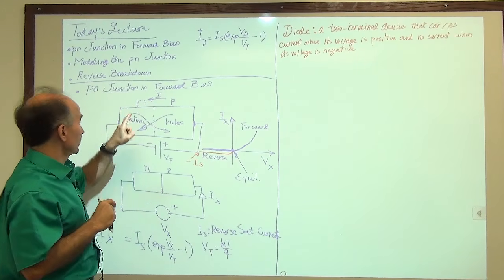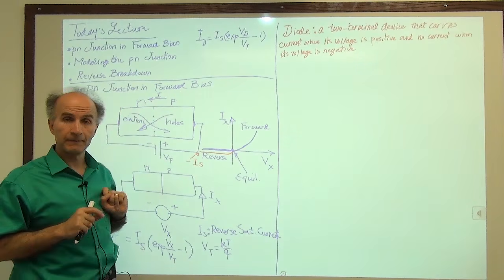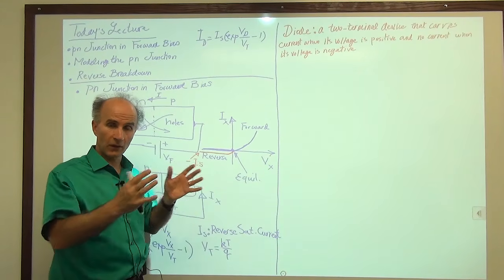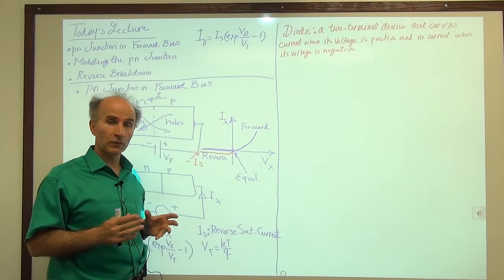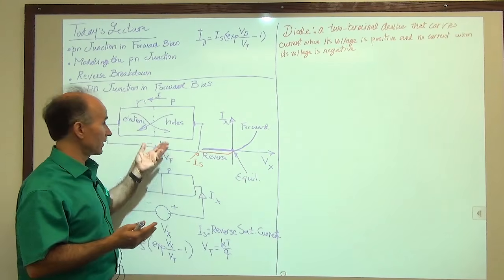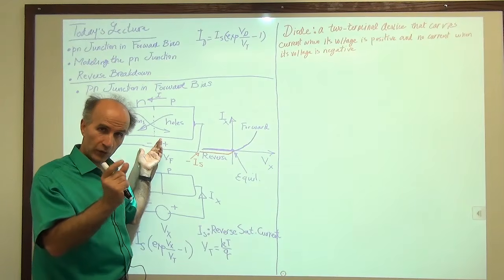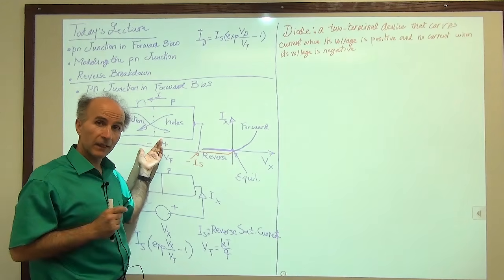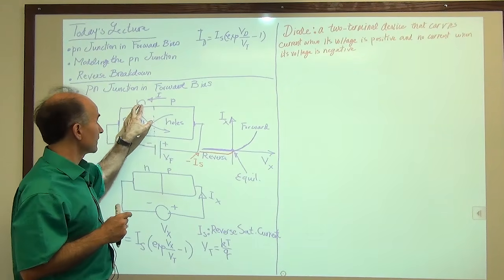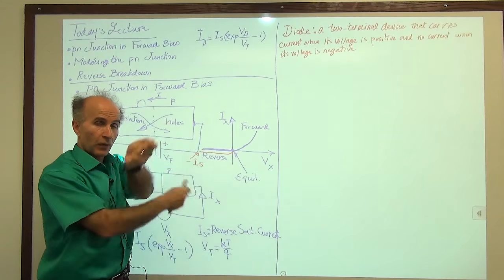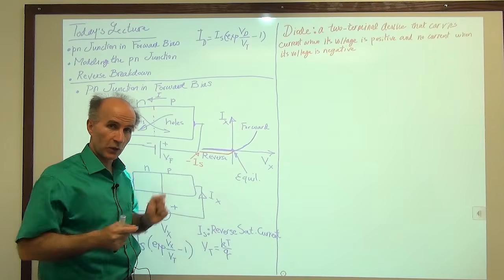So, in other words, we have to distinguish between this guy and this guy. Now, in our circuits, we don't want to draw a Pn junction all the time. So we will create a symbol for the Pn junction that, first of all, is much easier to draw, much more compact, and second, it distinguishes between the N side and the P side, so that when we apply a positive voltage or a negative voltage, we know which one is which.